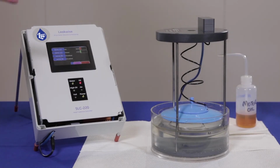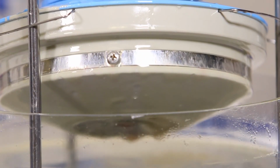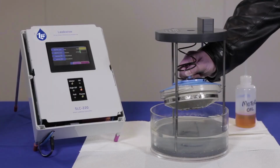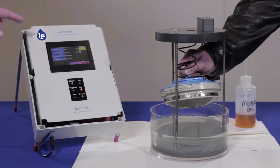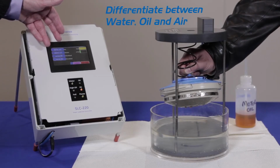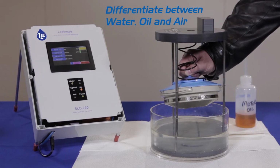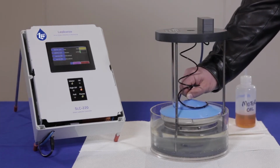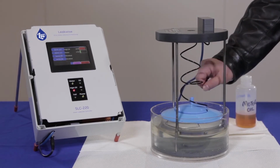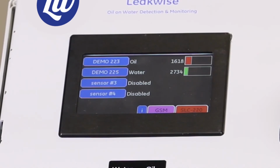In fact, if you look at the sensor closely, you'll see that the detecting antennae is coated in the motor oil. You'll also see, if you look on the display here, that it's now telling me my sensor's in air. The technology will do that. It'll differentiate between water, any insoluble oil, and air. If we go back into the water, you'll now see we're back showing the oil.